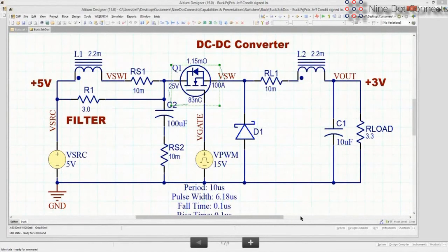on and turning off. And obviously, there is a lot of energy at or around that frequency and harmonics directly above that. So if I have a square wave at 100 kilohertz, then I'm going to have a lot of 100 kilohertz energy and 300 kilohertz energy and 500 kilohertz energy for mostly the odd harmonics. And so you're going to have quite a few, probably at least 20 harmonics to deal with.